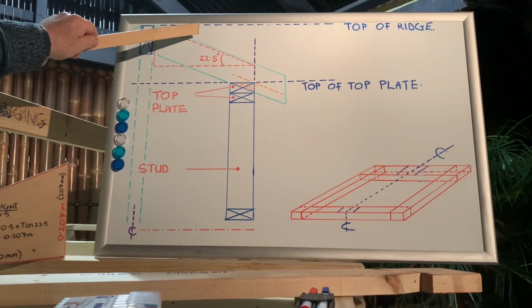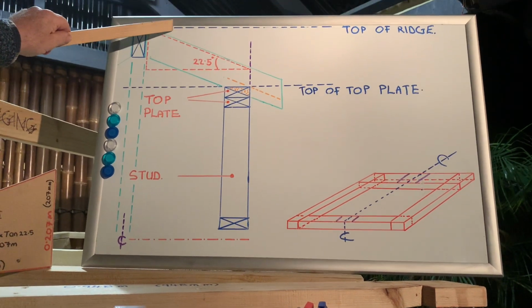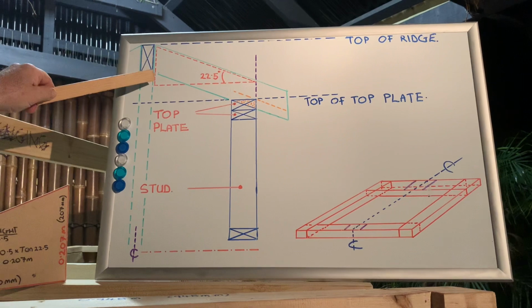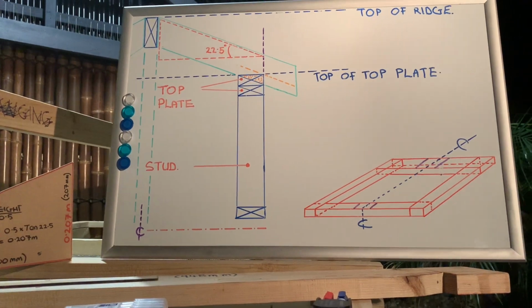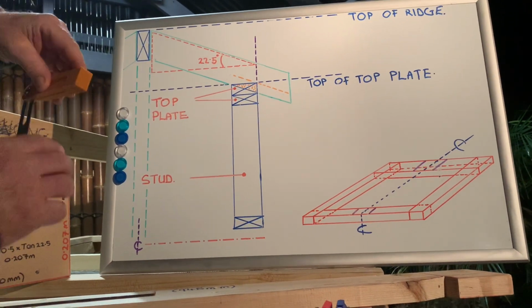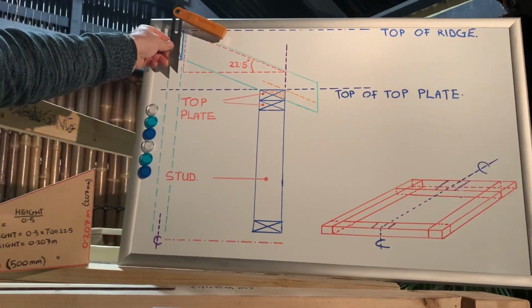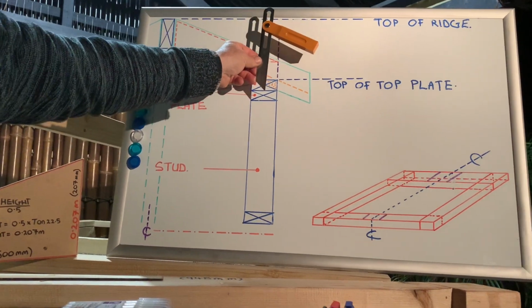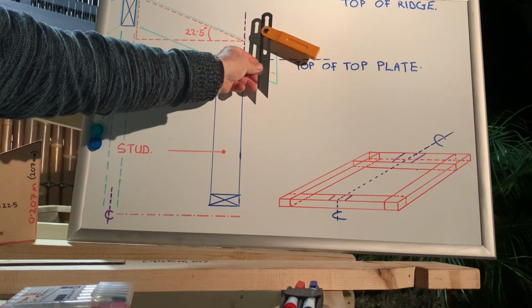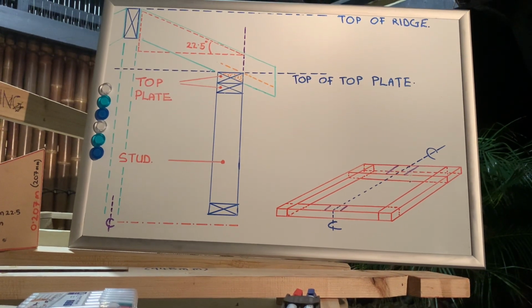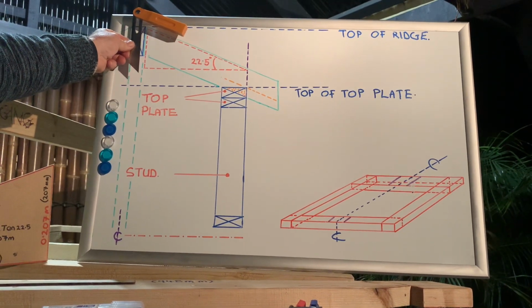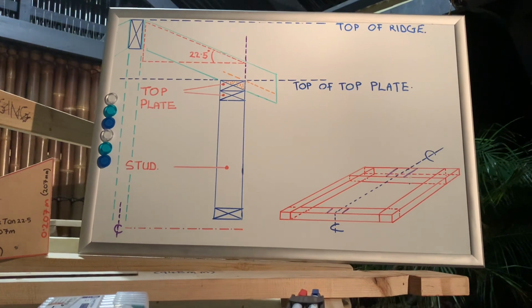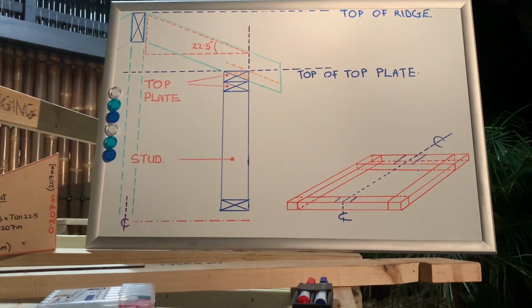And I showed you last time, we would put our gauge at the top and we would hold it up like that. Just as an example, I've got it here. We would put the gauge up like that and hold it like that. We would do the same thing there and there, and that's how we got our gauge. And remember, our vertical is our plumb. So when we're talking plumb, we're talking about being vertically level.